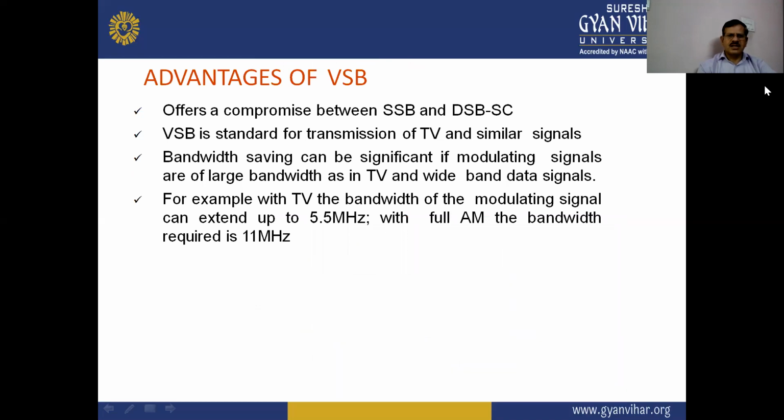What is the advantage of VSB? There are different advantages of VSB. First, VSB offers a compromise between SSB and DSB-SC, or single sideband and double sideband suppressed carrier signals. VSB is the standard for transmission of TV and similar signals, so VSB is generally used for transmission in television systems.